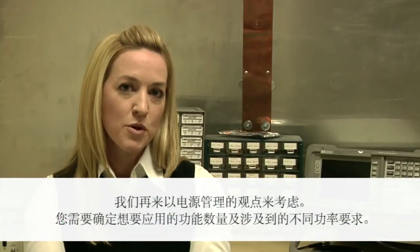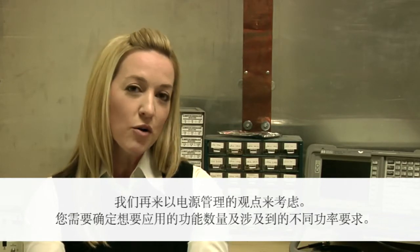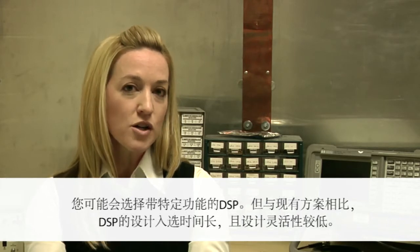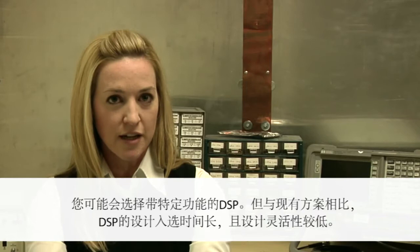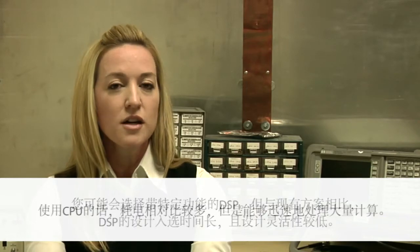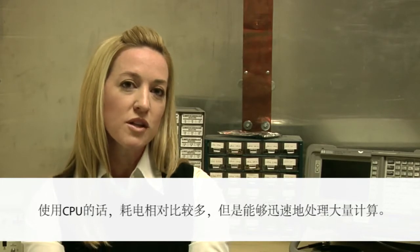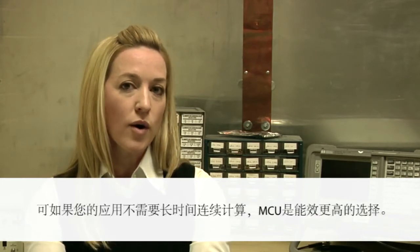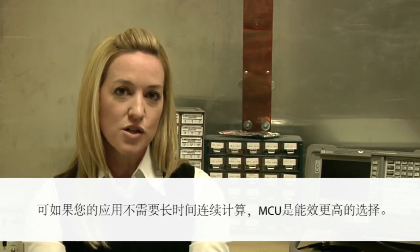From a power management perspective, you need to determine the number of functions you want to implement and the different power requirements involved. You may be able to use a DSP with specific functions, but it requires longer design-in time and less design flexibility than an off-the-shelf solution. If you use a CPU, it requires a bit more power, but it can accomplish a lot of calculations at one time. However, if your application does not require continuous calculations, a microcontroller is likely a more power-efficient choice.